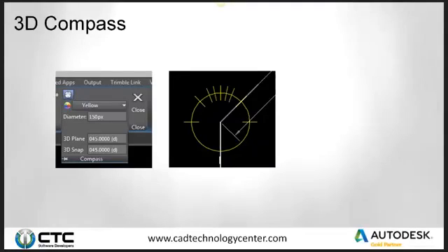We'll go 3 points. I've got a start point, an angle point, and then my end point, and maybe the angle between them is going to be 30 degrees instead of 45 or 22.5. Well, by putting in a 45-degree elbow and then using that deflection, I'd have the ability to angle my pipe over that 400 feet to make up that extra 10 degrees.